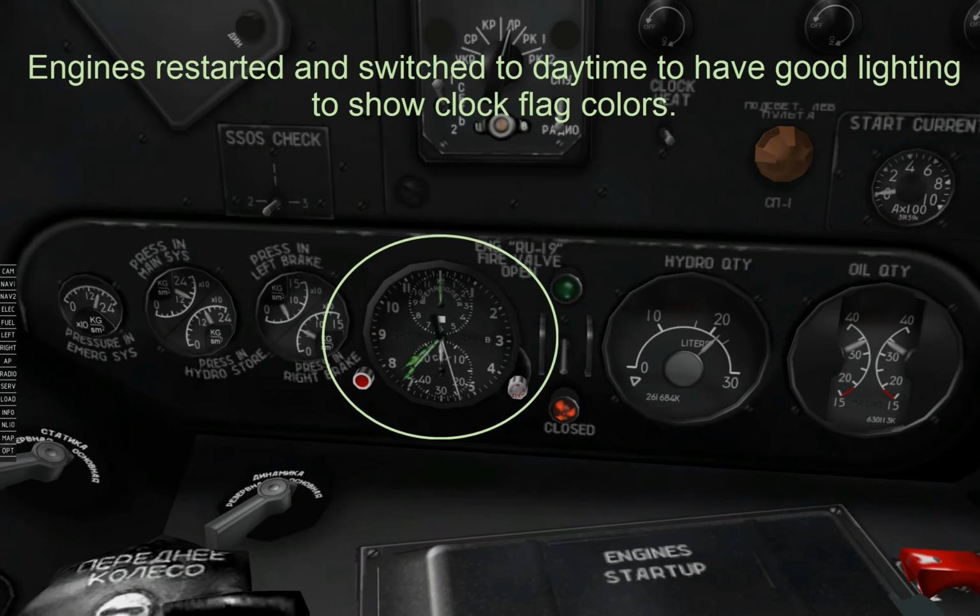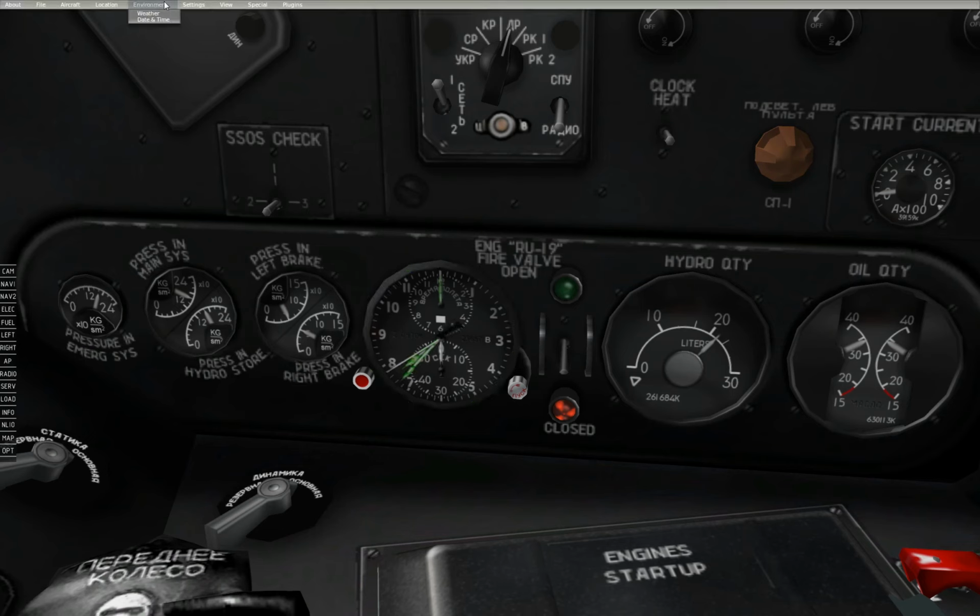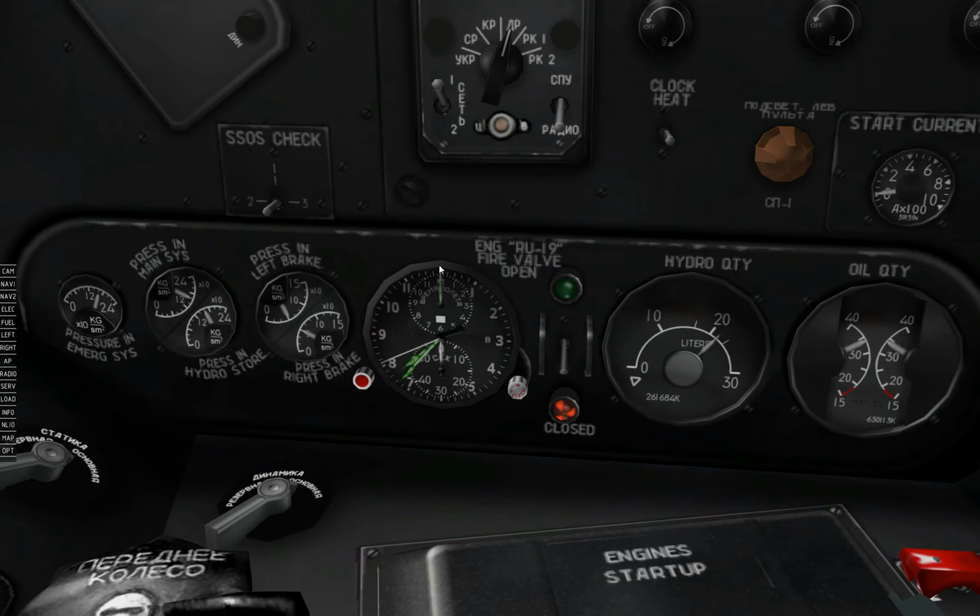This is the ACHS-1 chronometer. It is a popular aviation clock used in older Russian aircraft. The bigger main dial shows the time of day in Zulu time, not the local time. So if I show you here, even though my local time right now is 12:36, Zulu time is 07:36, and therefore that is what the big dial around the clock is showing.